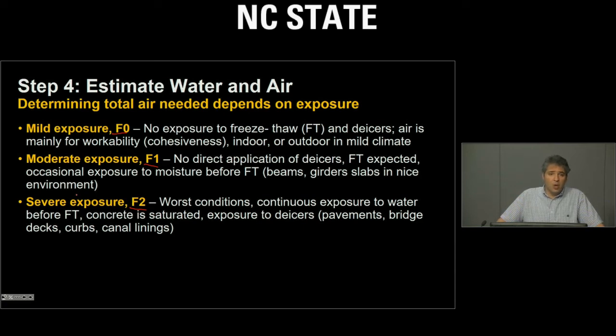So mild exposure is an exposure where our concrete during the service life is not exposed to freeze and thaw cycles. It is not exposed to de-icer. So in this particular case, you already know that bridge deck concrete is not mild exposure. For example, a bridge in North Carolina or a bridge in New York will be exposed to freeze and thaw and will be exposed to de-icer salt.